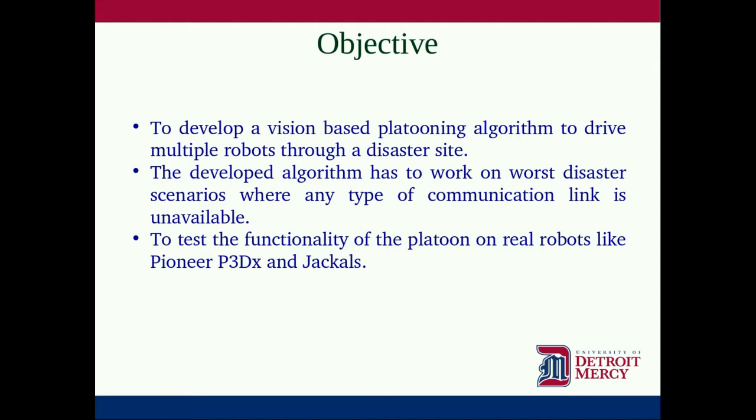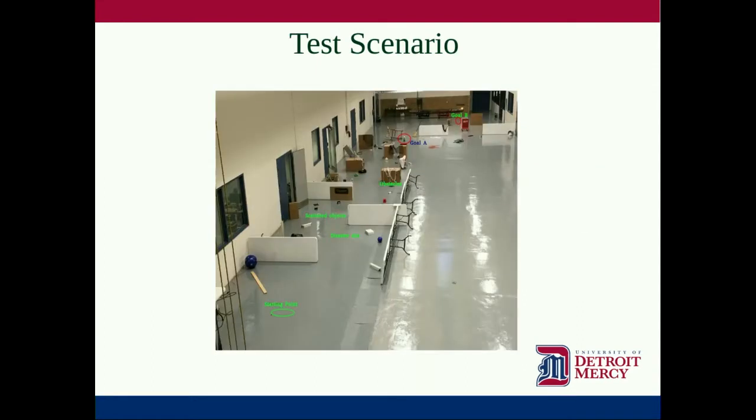The position information of the leader robot was detected by a Kinect camera. All the follower robots in the platoon subscribe to the depth information of the robot that is in front of it. The linear and angular velocities are controlled based on this depth info. A navigation algorithm named FISVFH has been used for navigating the leader to the desired location. The algorithm has been tested in different scenarios, and the details of the tested scenarios will be demonstrated now.